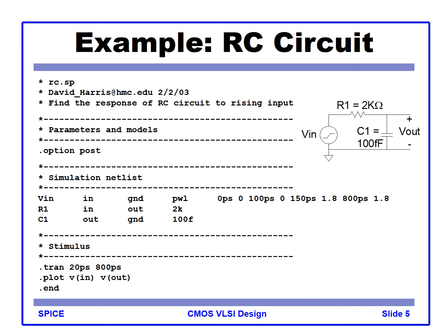This is an example of a SPICE deck. We have a simple voltage source here, a resistor and a capacitor. So we have three components in the network, so we define three: 1, 2, 3. The first one is the module name here, and this is a net definition.